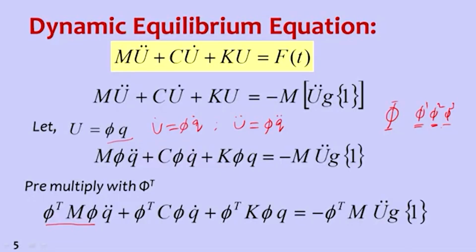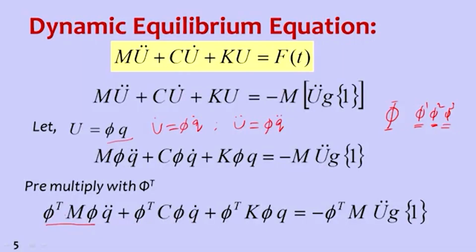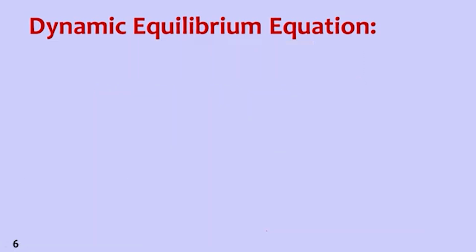In the previous classes, we have discussed that these mode shapes are orthogonal to each other. Each mode shape is perpendicular to the other mode shapes. If you look at it graphically, you can easily visualize that each mode shape is perpendicular to the others. So using the orthogonality principle of the mode shapes, if we pre-multiply and post-multiply the matrices with the mode shapes, we get the diagonal matrix of M, diagonal matrix of C and diagonal matrix of K. That will decouple the coupled equations.